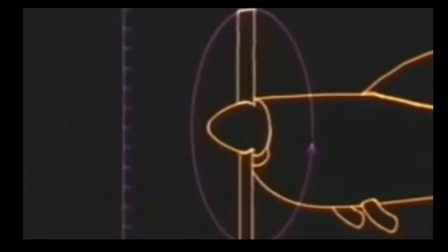During flight, its motion will comprise rotational velocity and forward velocity. With the propeller stationary, any forward velocity is that of the aircraft, the true airspeed. But a rotating propeller accelerates air and produces the induced flow. The sum of the TAS and the induced flow is the total inflow.